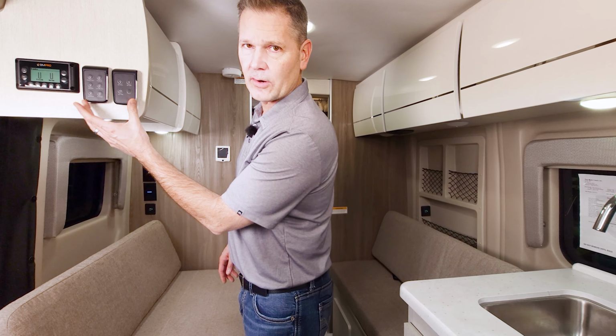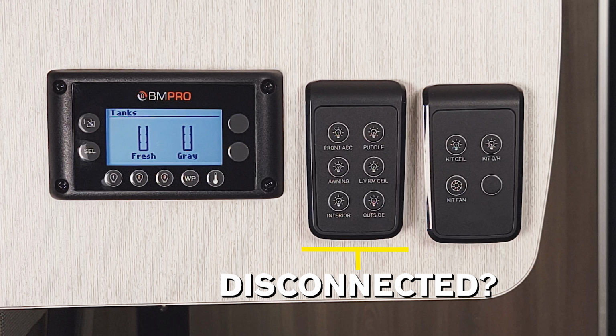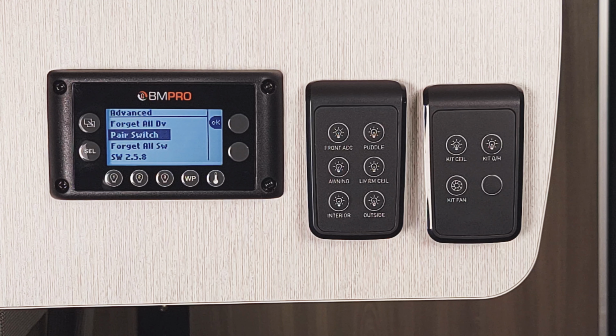Now we're going to go over the remotes. These switches are remoted into the main panel we just went over, and they control all the lighting in your van, both inside and out. In this video, there's a second remote, and this is going to have buttons for the kitchen fan. Now, in the event one of your wall switches gets disconnected, it is real easy to pair it back up. So hop back over to the main panel, navigate to the Advanced tab, and you're going to see the option called Pair a Wall Switch. On the remote you want to pair back up, simply press any two buttons at the same time. This pairs the remote right back up, and now you're back in business.